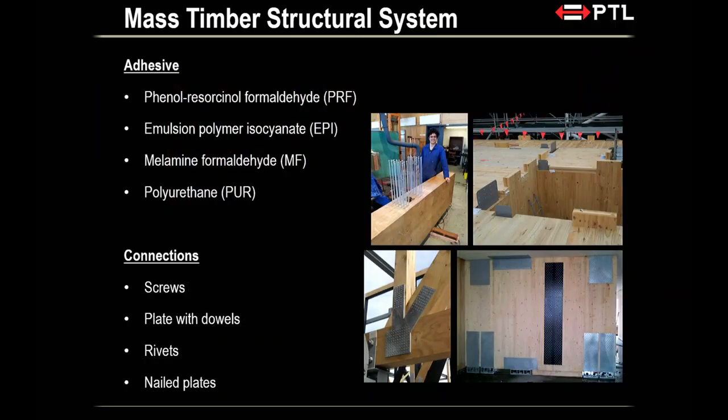Now, the thing here is the lamella. All these mass timber products have layers and layers. I call them the lamella. They don't just come together, they need to be held together. So as part of the system, you need to think about what kind of adhesive is used for this timber. From a fire perspective, there are different adhesives. There are adhesives that perform well under heat, and then there are adhesives that don't perform so well under heat. They will fail, and as a result, your layers will start to fall apart, start to delaminate.